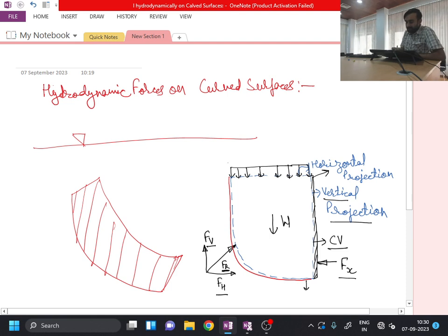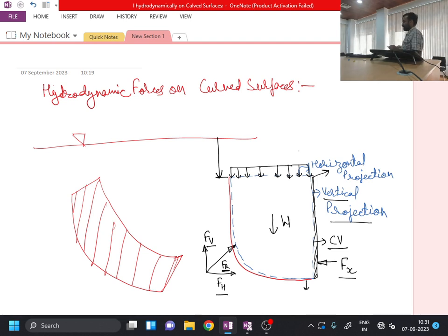Okay, so here because it is already submerged within the free surface, the magnitude of the pressure will be slightly higher than the free surface pressure depending upon its depth. So that's why I am considering this black colored pressure distribution which I have drawn over here, because now the projection is horizontal and we are not changing the elevation for the horizontal projected area.